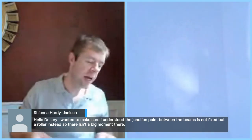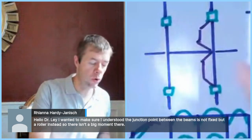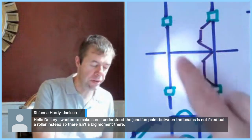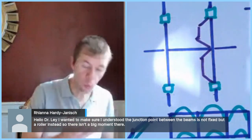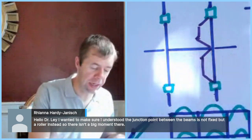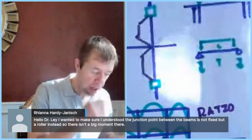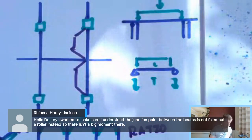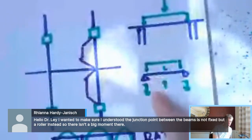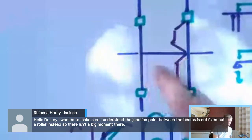I would treat this as a roller, or a pin and a roller, for this beam, and that way you don't have a lot of moment there. If you don't want to do that, you could treat this as a continuous beam, and you would do everything else I told you before. Everything would end up being the same. This would just look a little bit more complicated. But I would treat this as a pin and a roller and just put point loads there. That's the way I would work it.